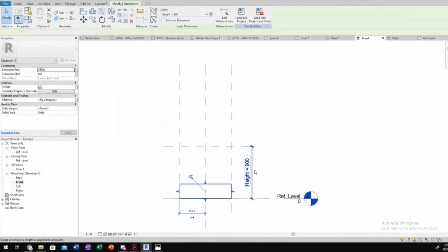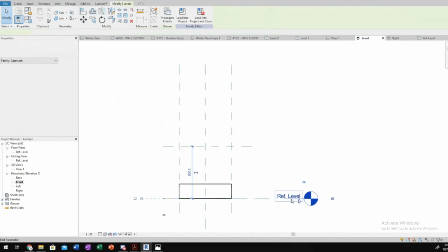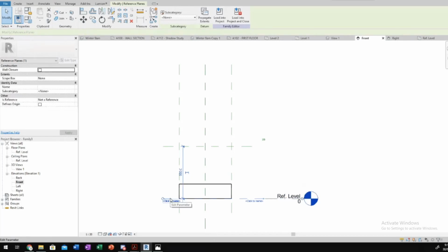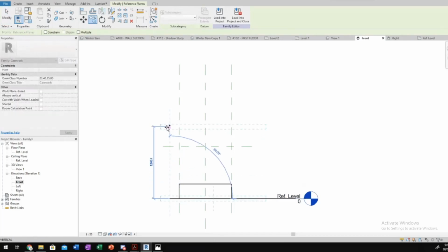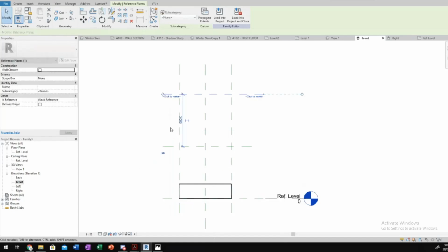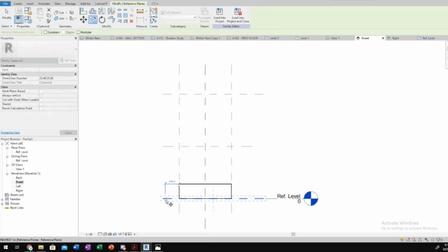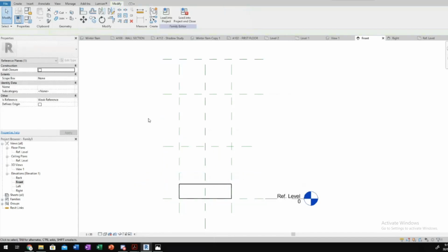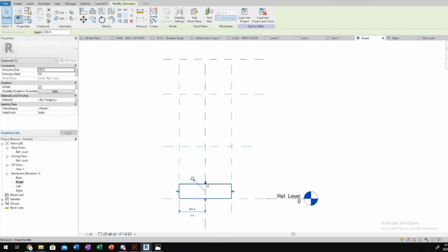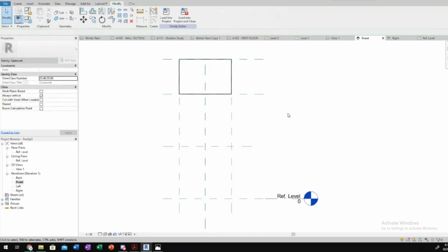But what if I want to do a cabinet, right? So let's delete that. I'm just going to move this out the way. Now, I'm going to copy. This is just a reference line. It's like a guide or a grid, so you won't see it, but it helps you design stuff. So typically cabinets start at 1800, and then they'll go to the top of the roof, which could be 2400, for example. So now I can take this extrusion that I made and drop it between these two.